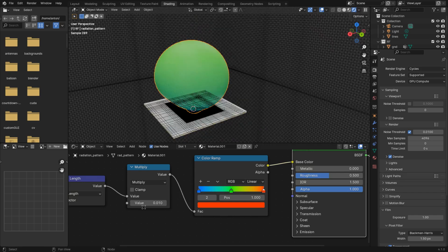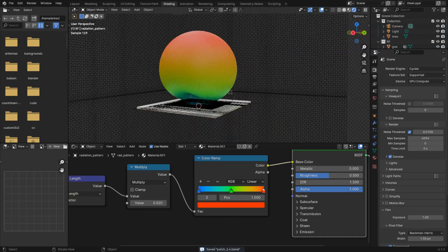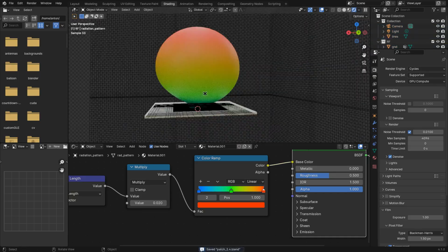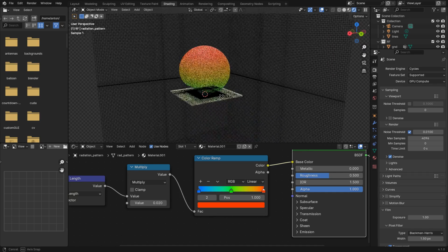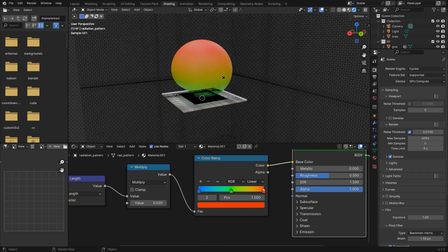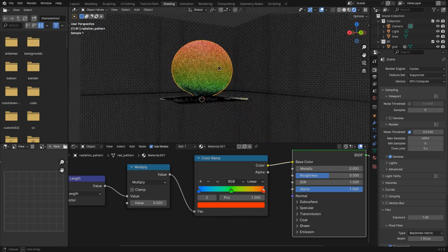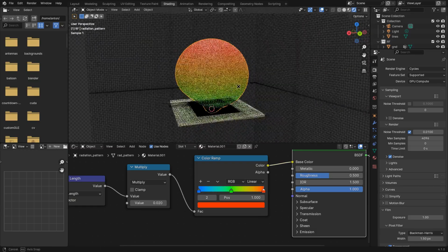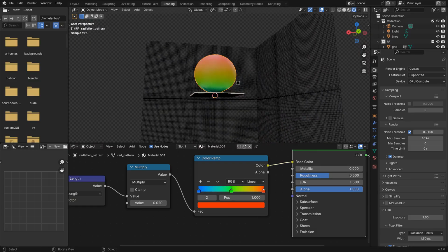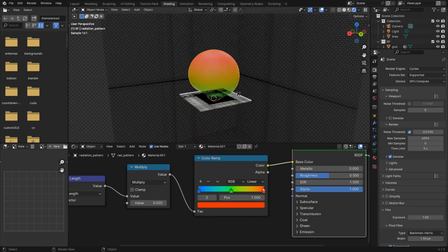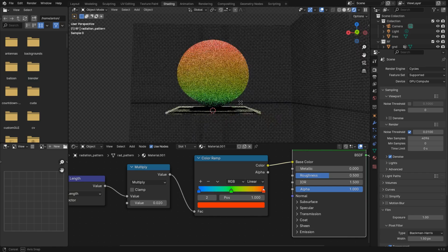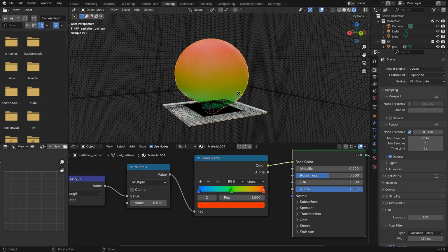Still not quite there. 0.15. 0.2, yeah, that's it. Okay, and this gives you a nice visualization of your radiation pattern for your antenna. This, by the way, has no scale because it's a far field view, so its scale is not in any way related to the scale of the antenna, so you just want to display it in a visually pleasing way.